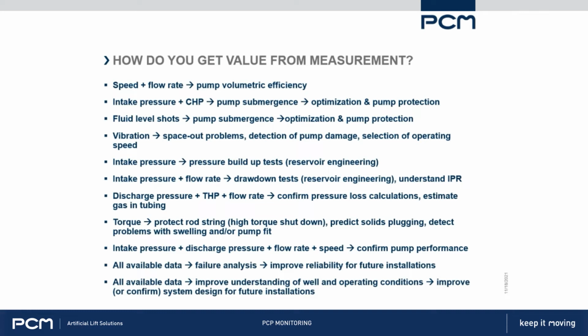But for example, if you want to know what your pump's volumetric efficiency is, because I need to know if I've got the right rotor size, if I have the speed and the flow rate, I can calculate the efficiency, and then I can decide is that too high or too low. If I know the differential pressure on the pump, and the efficiency at the same time, I can figure out where I am on the pump curve and decide if, again, is my rotor sized properly for that.